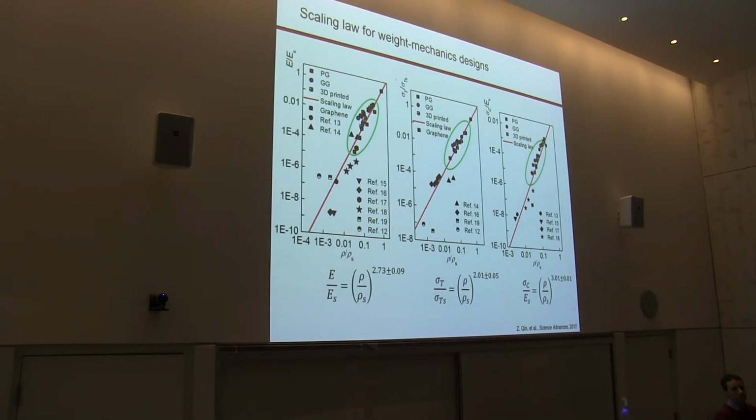Once it merges and fuses together, the carbon atoms still like to stay in a surface. If it can reach high density, it should be a continuous surface, and you need to maximize the usage of the carbon atoms. Then you need a minimal surface within any boundary. The mathematical description of the gyroid structure is quite satisfying. Then I do the 3D printing, and for the scaling law, I find agreement between this printed model and the simulation result of the graphene.